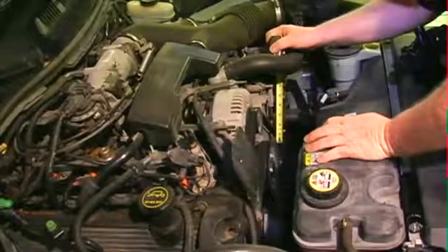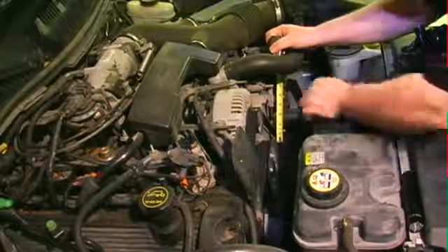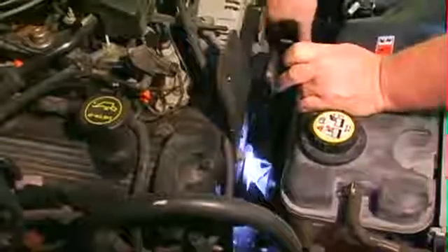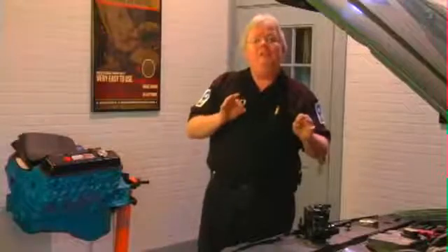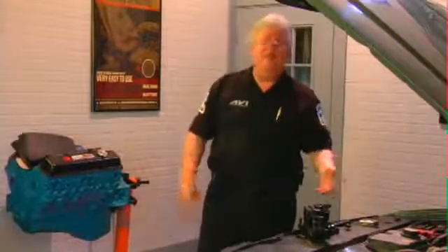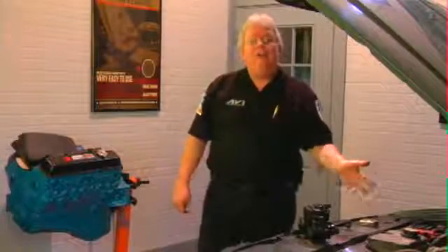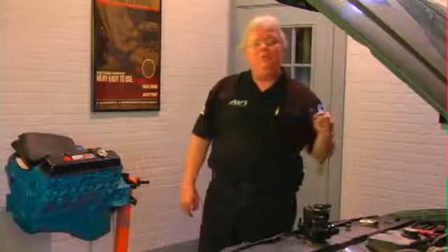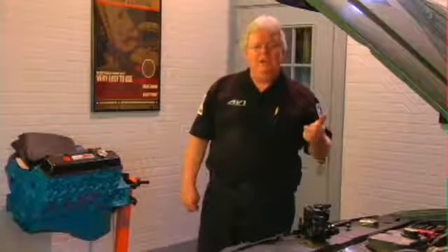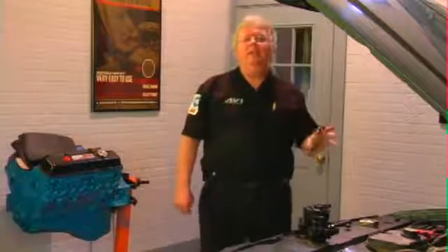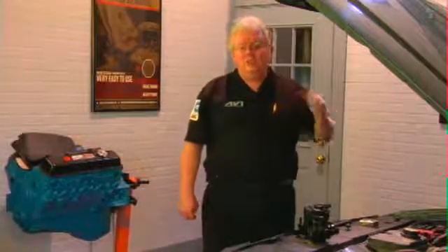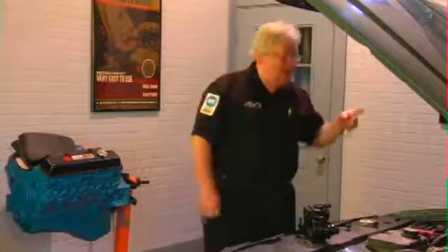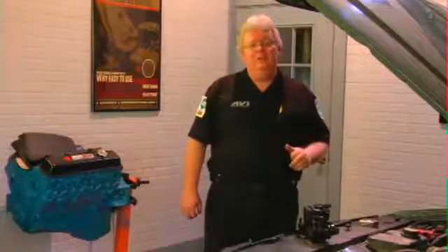Now, you may think, well, I could push it further than that. Certainly you could. Look how far you could push it, but also look what's going on with the tensioner. So deflect the belt to the point right prior to the tensioner starting to move, and then make that measurement, and that's a tight enough belt. Now, they're not adjustable. Most vehicles with the serpentine belt have a tensioner, but the tensioner requires service and replacement periodically. If they get noisy, if they start wobbling, if the surface of the tensioner is not smooth, all those things you want to look at when you diagnose problems with power steering, because power steering is dependent on a good tensioner to keep it going.